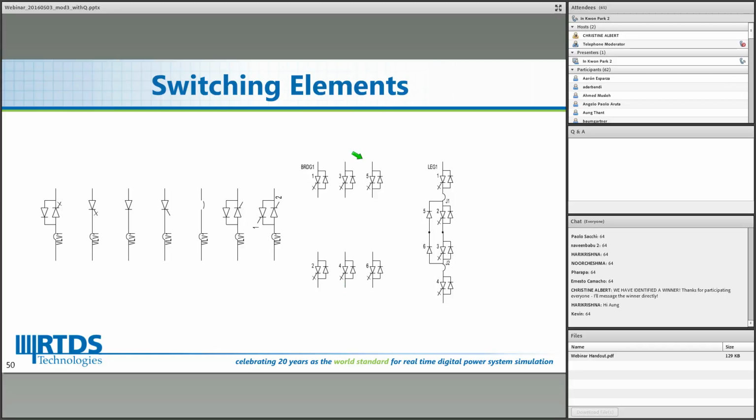That means we can save the necessary simulation time when it comes to running the real-time power electronics simulations with all these switching models. By using this bridge model, you can model the 2-level bridge, and by combining 3 of these, you can build a 3-phase, 3-level MPC bridge. Then again, we can save time in our real-time simulations.